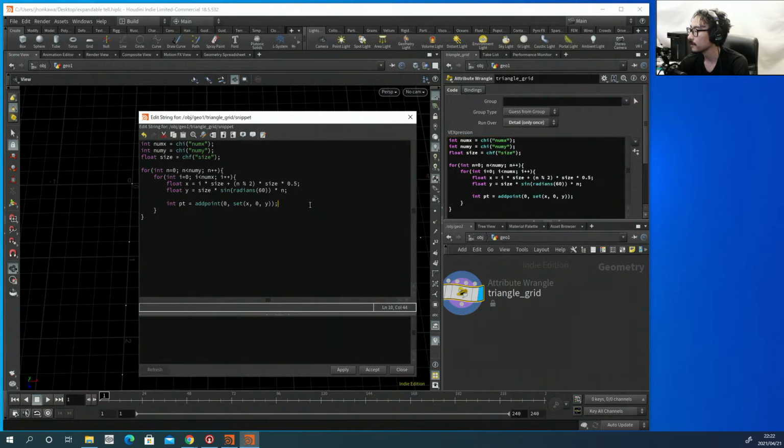First thing first. Just in case I might use the information like index i or index n, I'm going to have these as an attribute to each point. So set point attrib. I'm not sure if I'm going to use it later, but just in case. Attribute i, which indicates the number of the column at the point, to width i. Set point attrib 0 and pt n.